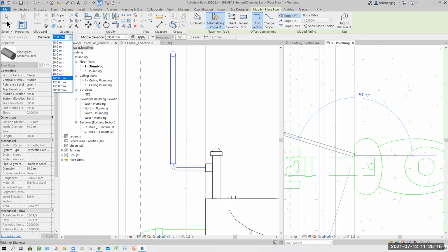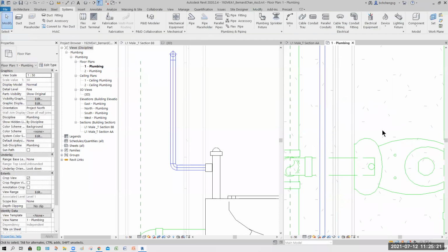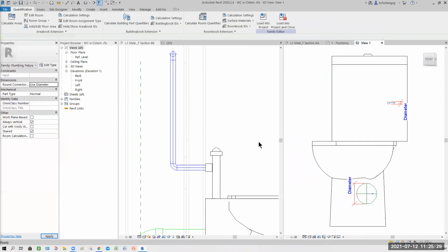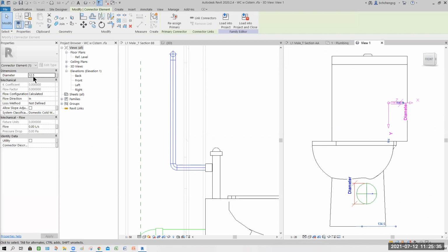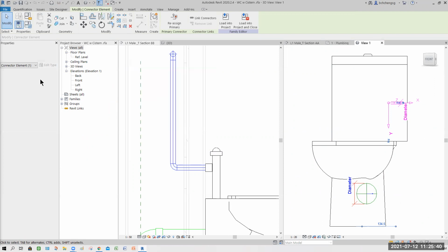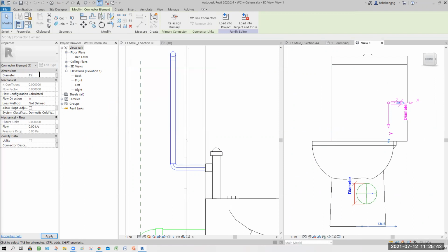So can we change this guy to a 12.5 pipe? Can, right? So if you don't draw it, just modify again. It's a good chance to practice all these changes. So this diameter here, select 12.5. You see, it's not connected to anything. So if you don't have it, just type in 15.